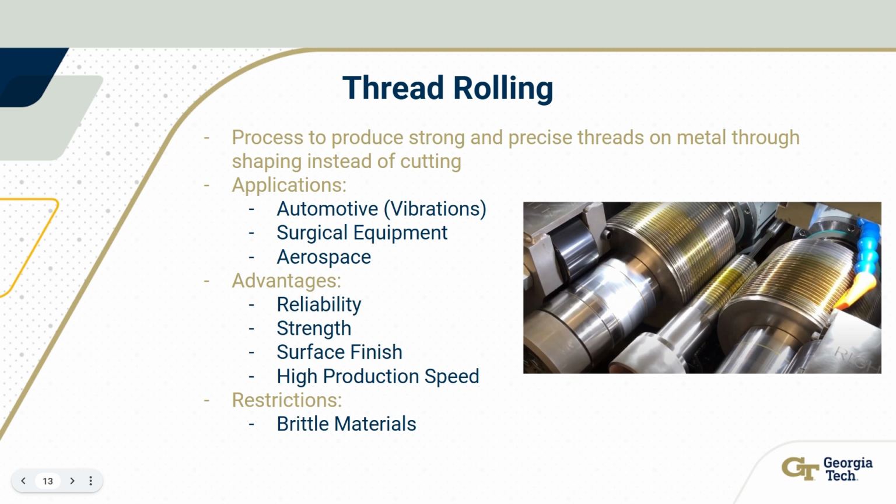And this is something that I specifically like because as part of my robotics team, we have to make a lot of threads. Sometimes I have had to get those threads machined, and I've opted for thread cutting, which sometimes does not meet the specifications we need, and sometimes we need to go for thread rolling for those stronger threads so that they won't break as easily.